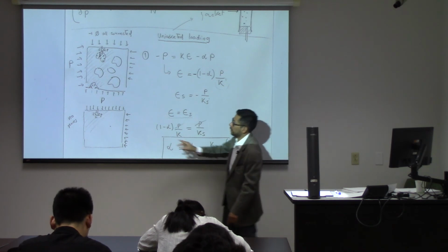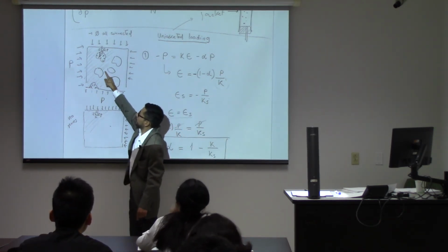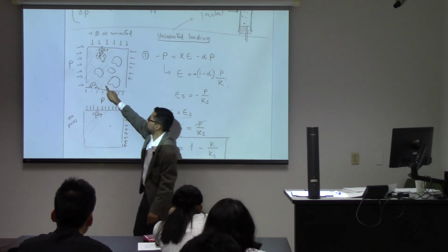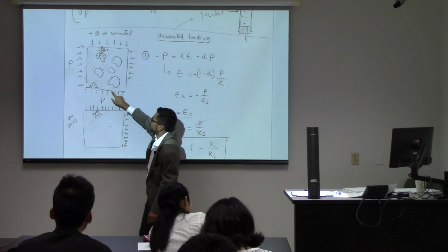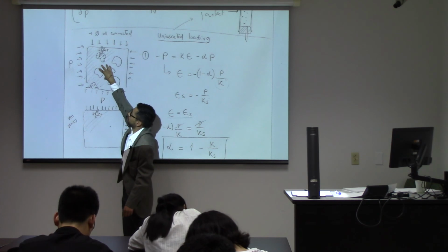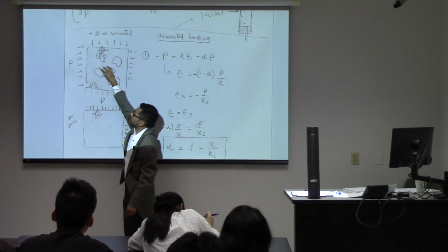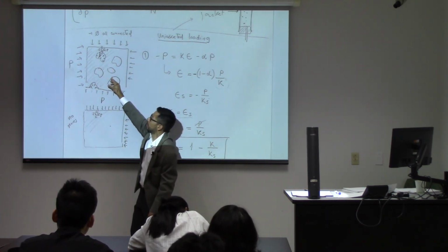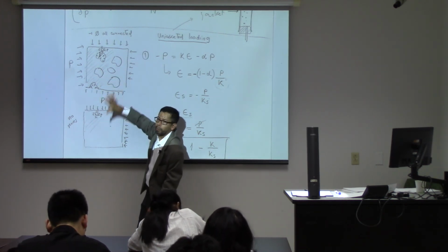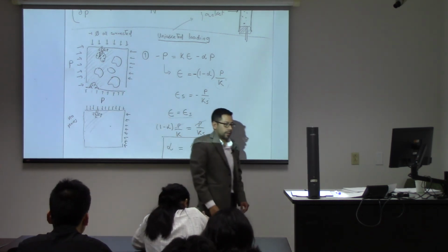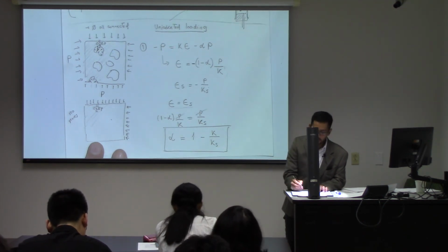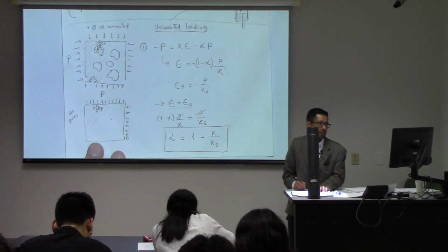The second thing is that the porous solid is isotropic. It has some holes, but it is isotropic and it's the same solid everywhere. Again, if I had, say, a section here of the solid which is different from this solid over here, that will take more stress than the neighboring solid and will not make the state of stress homogeneous everywhere in the porous solid. And also, I would not be able to arrive to this equation.